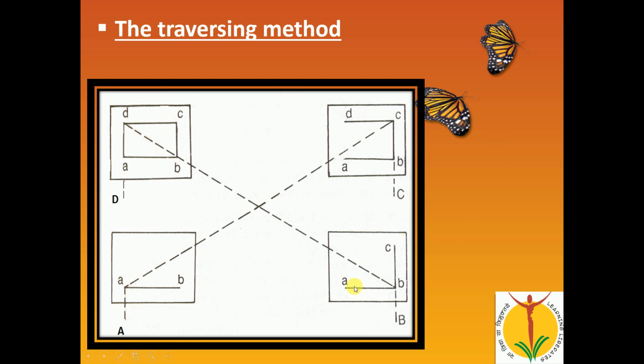So next, the alidade: you have to move to the point you have marked on the drawing sheet at C, and over that point you have to exactly take the ground point C, and with the alidade touching point D and bisecting the ranging rod at D, you can draw one line. Similarly, you have to shift the table exactly over station capital D by means of the plumb bob, and then with the alidade touching point D and bisecting the ranging rod, you can draw one line. So this completes your rectangle.